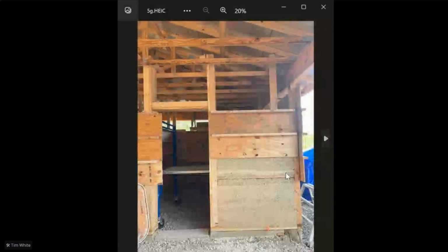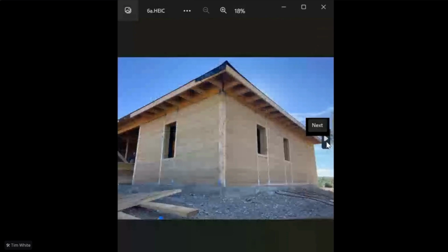Here's a hempcrete wall going up, and I wanted to show you how we have the forms on the side. So you can see how that 2x4 goes in and it literally locks it into place. On this system, we used our 2x4s attached to 2x10s for our interior walls. So it made a channel to attach that material into for the hempcrete. Worked out really great.